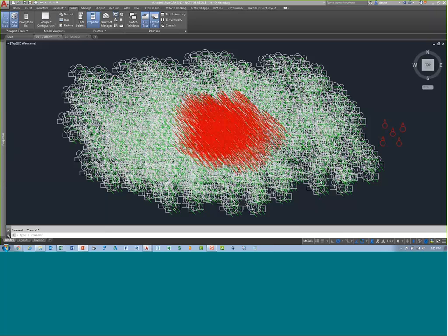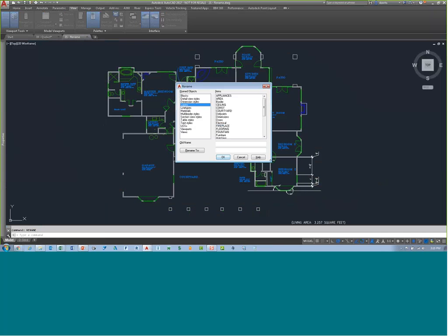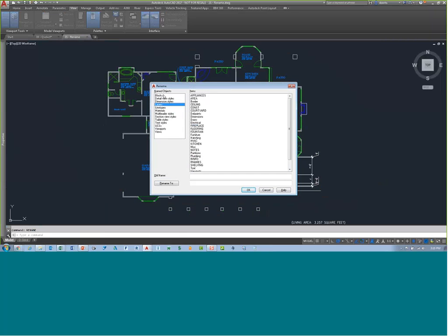Tooltip number 21, the rename command. So I have a drawing here, and I can just use rename, hit enter, and it opens up this dialog box, which you can also resize. And you can click any one of the categories of content that you need. So for example, under blocks, we have all these different blocks in here. So I can pick that door and rename it to DR999 and hit rename, and it renames it.